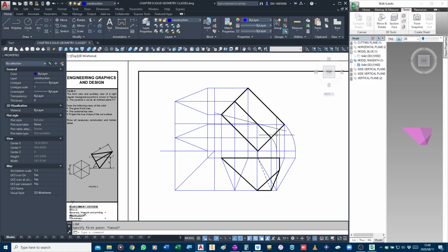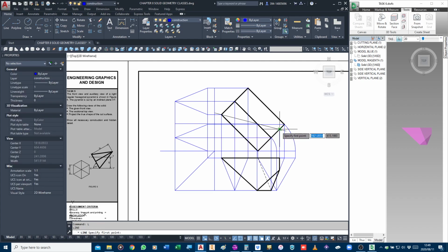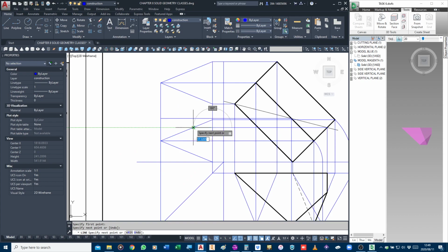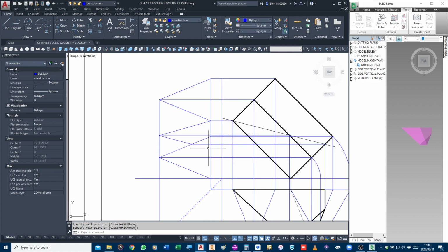Here again, cutting through the base. That line there represents both that line, where are we now? It's that line and then this line for the base, remember? So if I extend that from there to there, that's where it cuts through the base in the one point, the other point. There to there to there. So there again is my section. So that can be drawn in dark immediately.